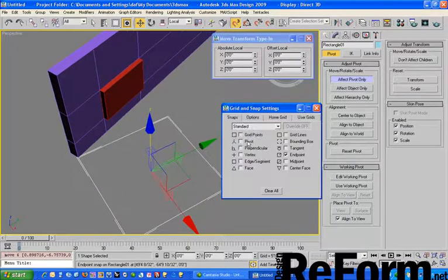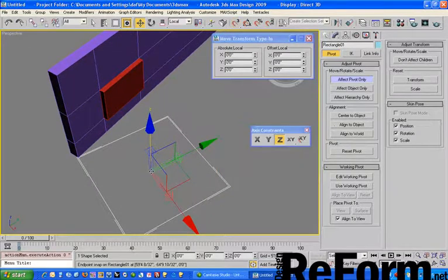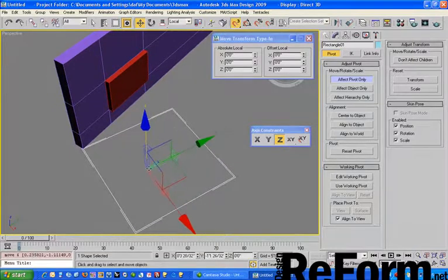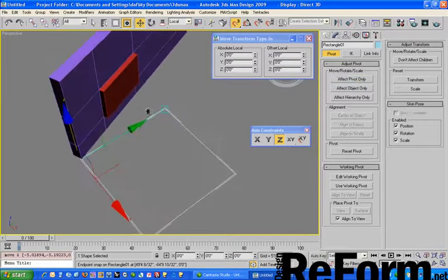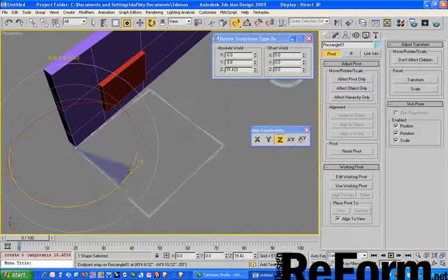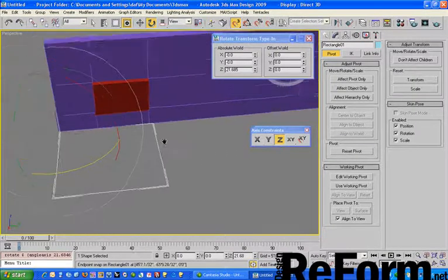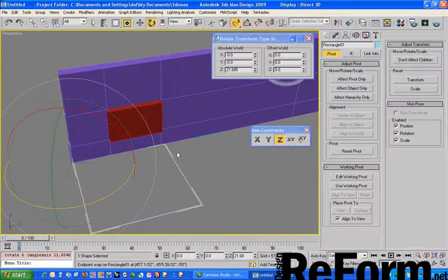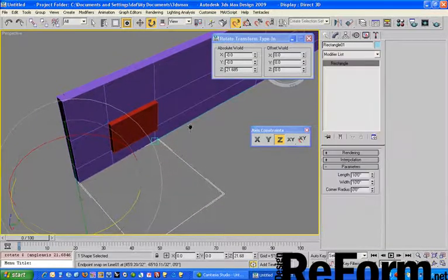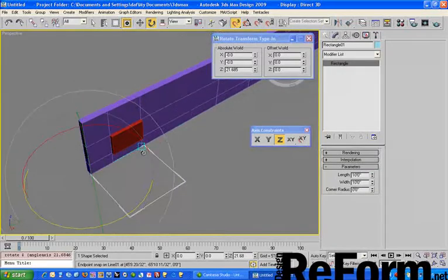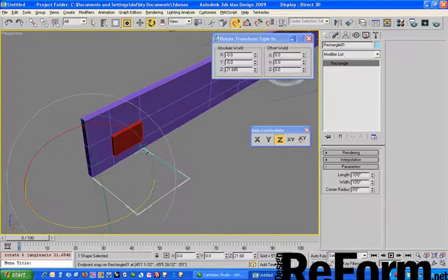So let's go ahead and turn on pivot as our snapping. And I'll hit S to turn the snapping on. You just kind of have to grab it and move it, and then the snap works. And then I'll rotate it. Again, not the most precise, but with some of the axis constraints we could get this to be 10 feet from this edge. And do that. So that's another way to kind of start to set up dimensions in Max, because we can't just draw out a line and make it 10 feet. We don't have a command line like we do in Rhino or in AutoCAD.